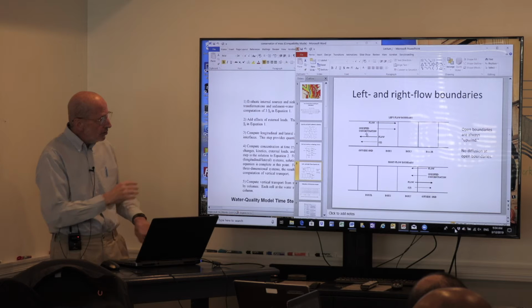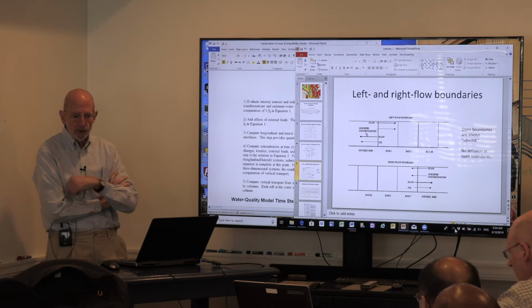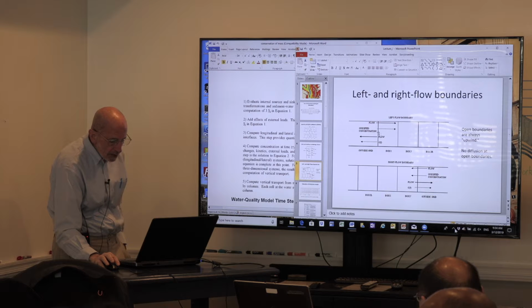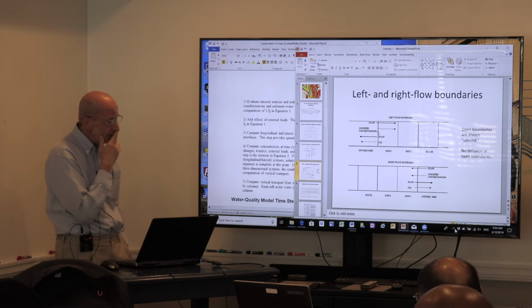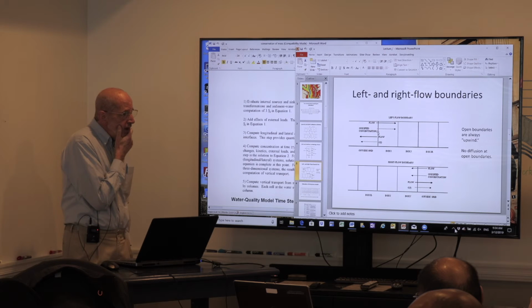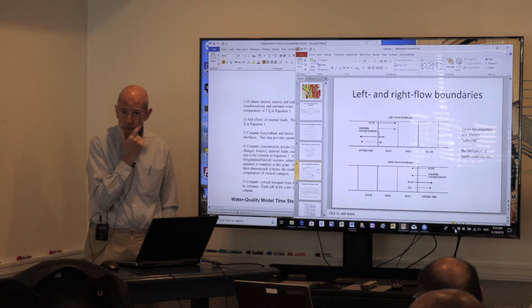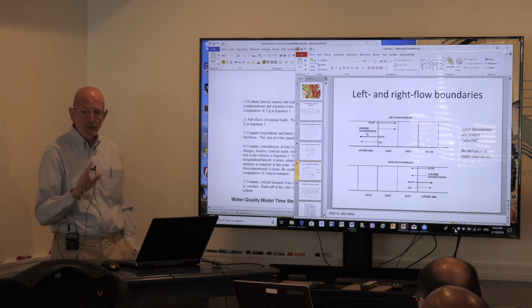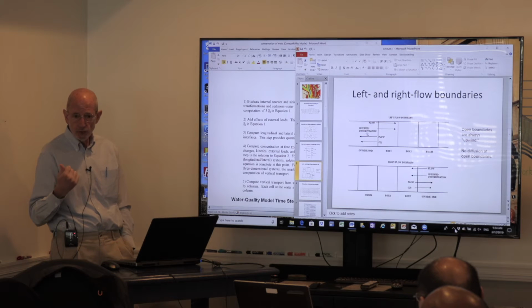Now, for a boundary condition, for the moment, we'll just say we have a boundary concentration. So what we want to do is specify the concentration at this most upstream face. That's what flows into the system. Now, we hardwire into the code at that face what we've been calling upwind. At an upstream boundary, this specified concentration is what flows into the system, period. Even if you opt to use QUICKEST.